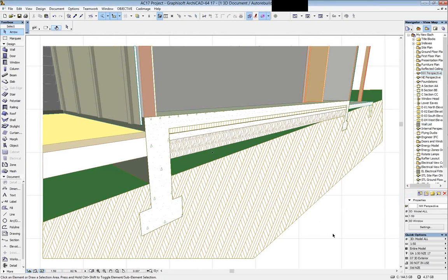Right click, 3D document, then you can add text and dimensions to it, and then you can export that as a view to your engineer, or as a view to your builder, or as a view to your building inspector for clarity. So if you don't know about 3D documents yet, please start using them in conjunction with 3D cutaways. Very, very powerful stuff. But as I said, it's not new.